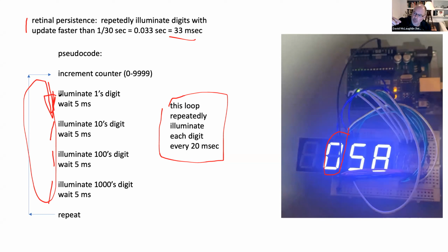Someone said, it doesn't look like I'm switching the lights off. How am I toggling them on and off? So take a look at this line here. What I'm doing here is I'm programming all the anodes, and then on this line down here, port B is equal to the complement of 1 shift left 2. What that's doing is it's making one of those enable pins low and all the rest high. That's what that pattern would be, right?